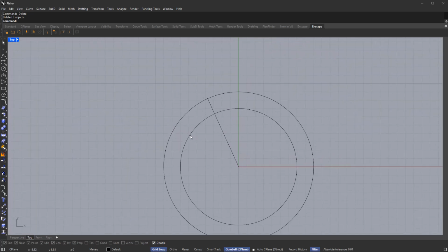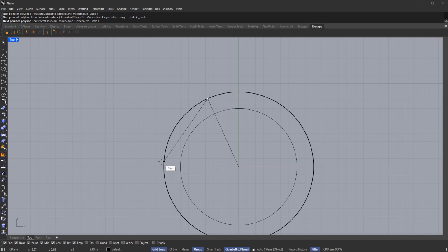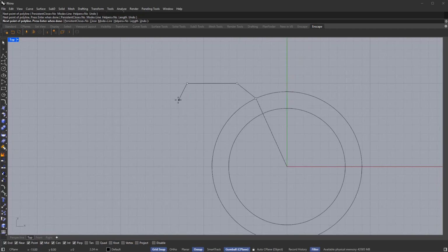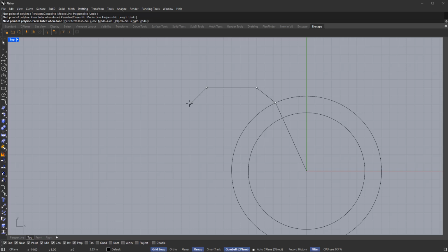And now let's zoom in a little bit and we can start drawing our slabs, again using a simple polyline. Now that we have this reference right here, enable grid snap and activate OSnap. Let's click on this first point and now again activate grid snap because I'm going to be heavily relying on the grid snap in order to draw this slab. And then let's count 6. So 1, 2, 3, 4, 5 and 6. Now let's take our curve 45 degrees this way, but this time counting 2 squares. Now 3 on the left side and 2 45 degrees downwards and so on. 3 and 2. And one last time, 3, and then we are going to be closing this first half of our slab.